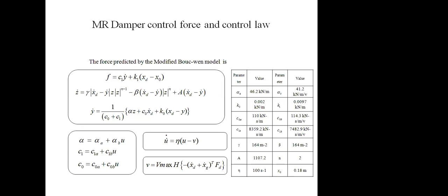As it is a semi-active damper, it will operate on battery power. As we observe, the voltage required is very low: 2 volt, 4 volt, 6 volt, 8 volt, whatever voltage we can utilize at that time, and according to that we can generate the force in the damper and we can save the structure.